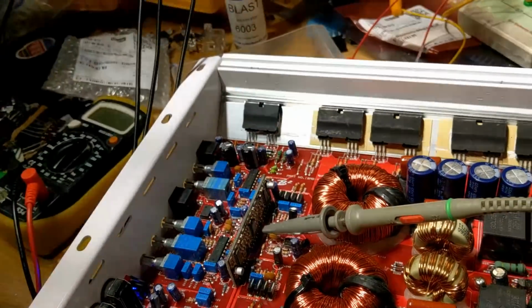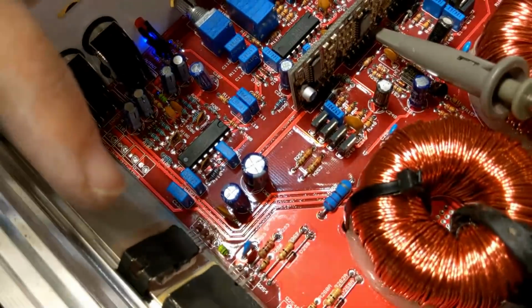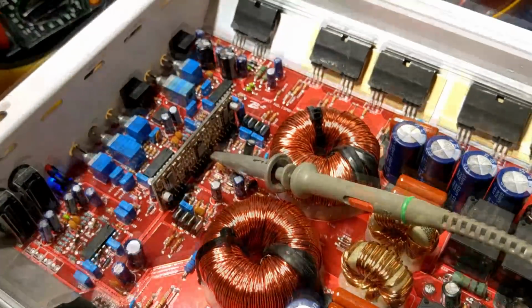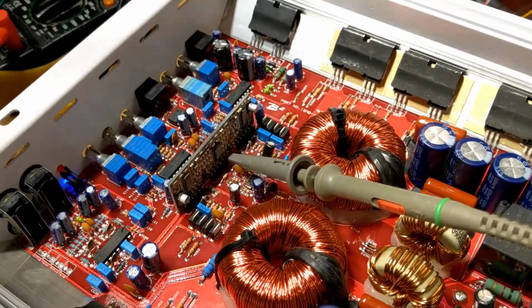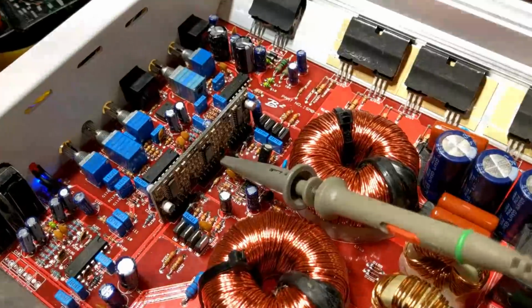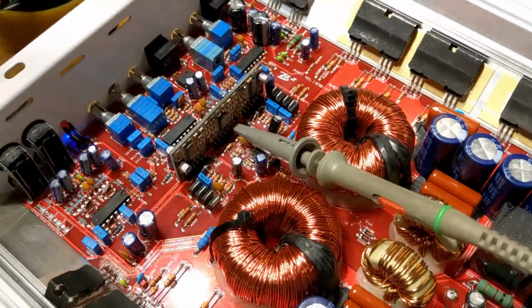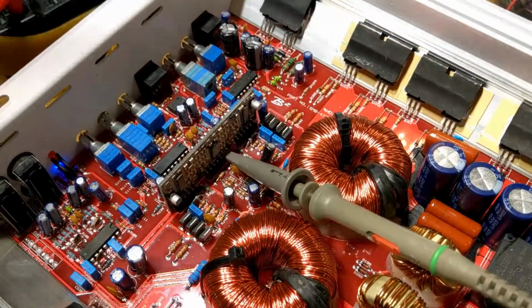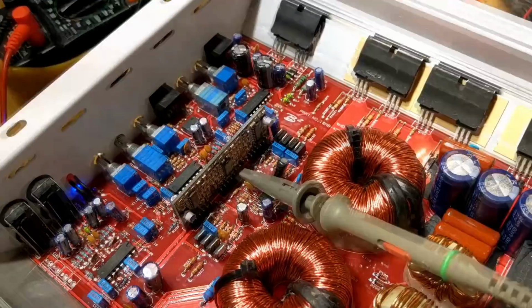So we can attach a fan to the heatsink here and just have it running off the 12 volt regulator here to feed 12 volts to the fan, so that it's constantly cooling down this circuit, and that will prevent it from going into protection mode. It's not obviously a decent fix, because there is still a problem with the circuit causing that to get so hot in the design. But at the moment, that's the best solution I can find for a quick fix for these. I hope that helps. Let me know if you have any questions.